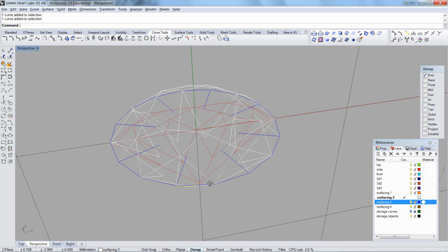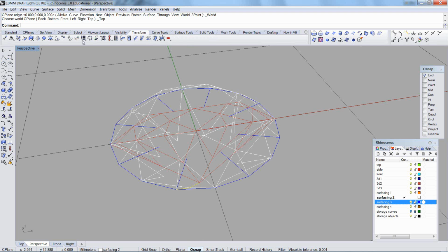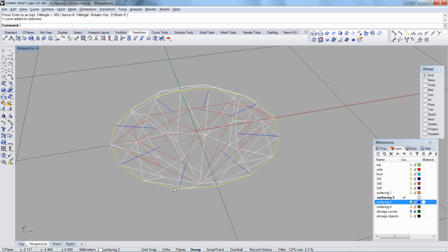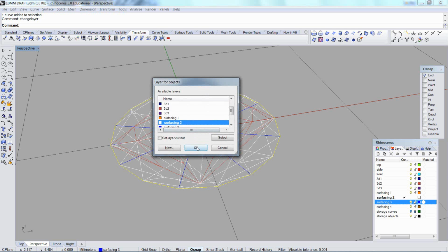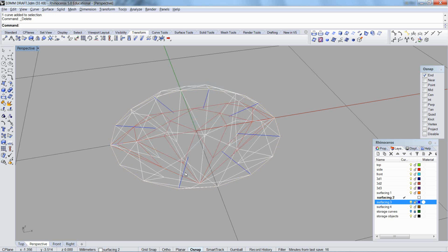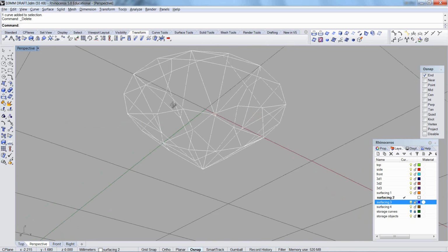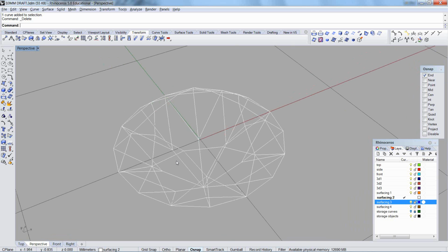Select both of these two that I drew, top C-plane, transform, polar array, center of array is 0, 8 items, 360, enter to accept. Put this on the drawing layer and delete these remaining lines from the bottom view. The flat ones, we don't need them anymore. And I do not need my front view. We're going to facet the stone.